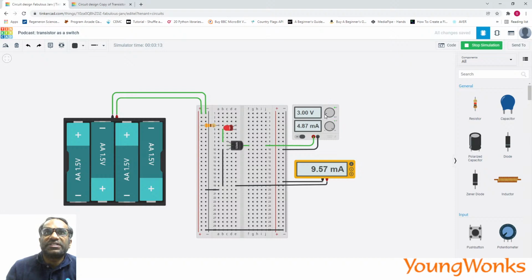Now I keep increasing it, and now there's going to be a section where as I increase, it increases much faster. But then there is going to be a point at which the rate of increase slows down and is not increasing as fast as the increase in the voltage. This is very noticeable because now I'm at 20 volts and you can only see 11.8 milliamperes.